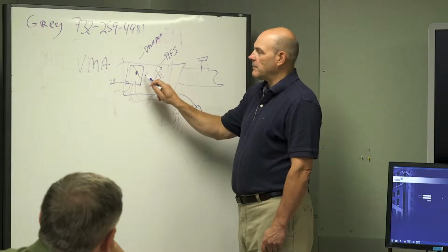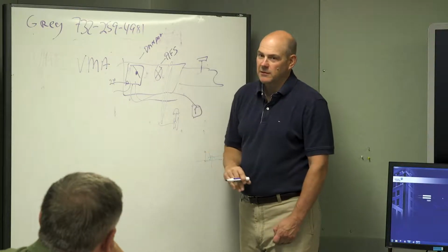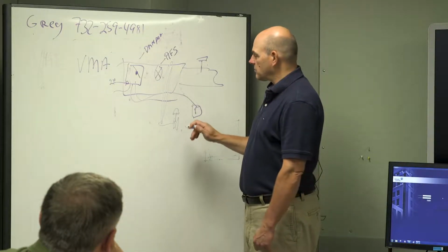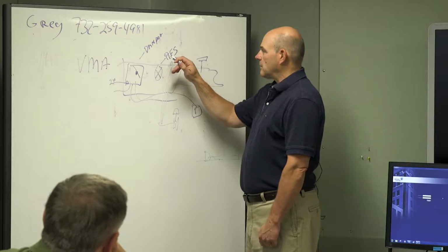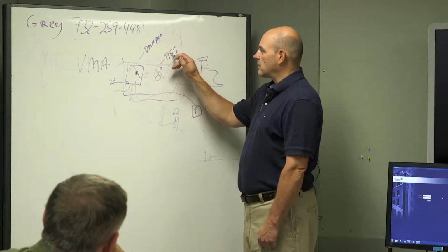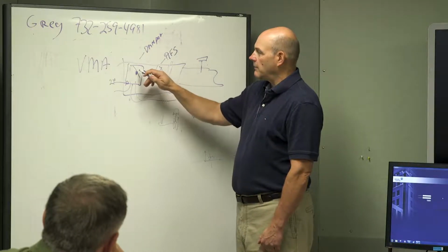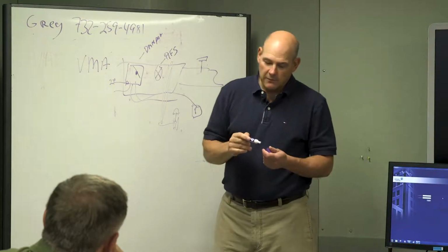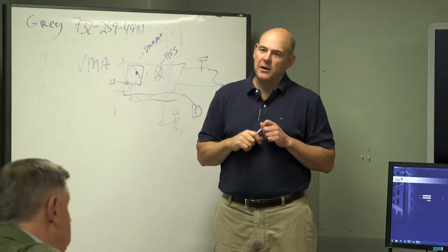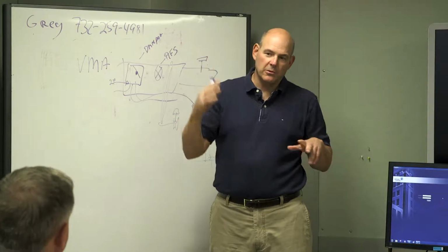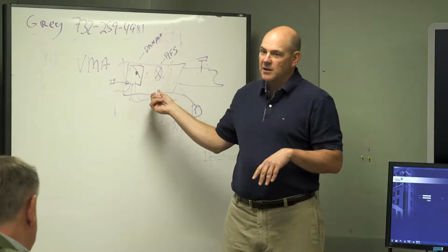So this VMA is in there, and it controls your room temperature, controls the valve, it monitors airflow, controls your airflow out, and monitors the damper. So we're going to get to that when we do the VAV boxes. You climb up a ladder, we'll show you with the VMA and everything that goes inside there.